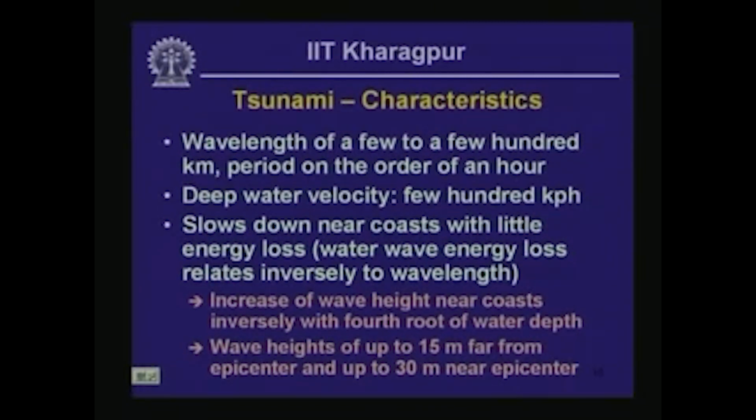Now, the energy associated with the propagation doesn't die down because of the very long wavelength of tsunami waves, so the energy remains constant. If the velocity goes down, you would expect the kinetic energy to go down as the velocity becomes smaller. So the water column is going to pile up in order to make up for the loss of kinetic energy.